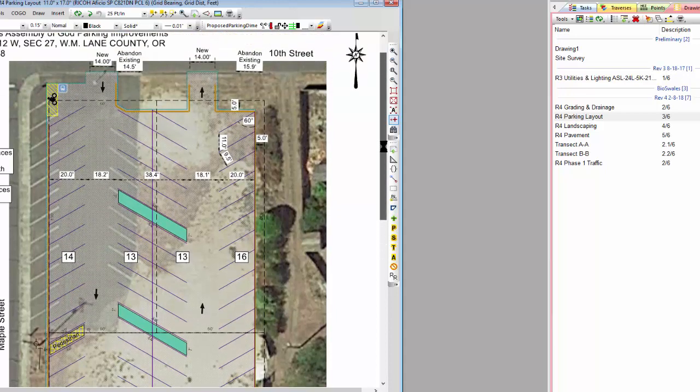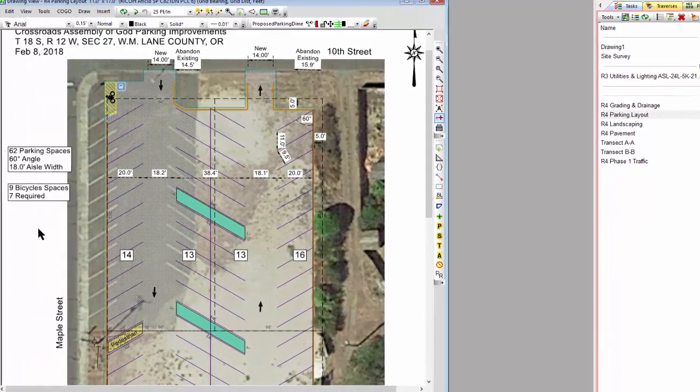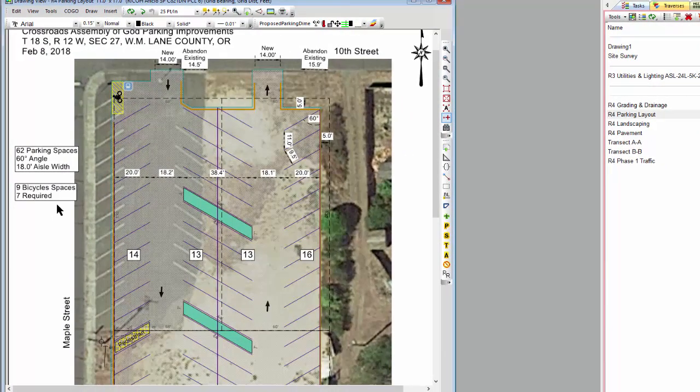The city also says for every so many parking spaces, you need to provide so many bike parking spaces. So we're providing 9 bicycle spaces, 7 are a required number. And they do interesting things like they have to be as close to the church, which is west of us here, as the nearest parking space. They have to be lighted, they have to be signed, they have to have certain access. And if you notice in this photo here, I've got some existing pavement here. We're actually going to pull out this pavement back from the sidewalk and use that for a bioswale.